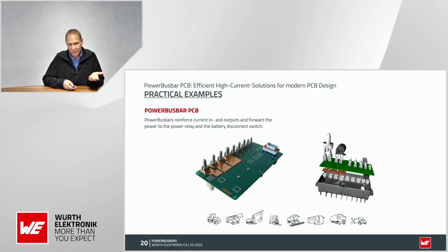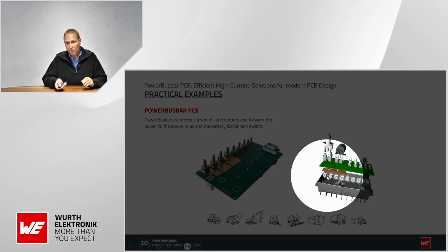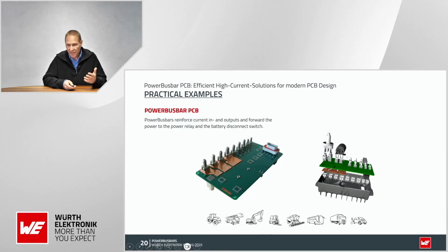So you have the bus bar on the top of the PCB and also on the bottom of the PCB. So you also have a compact design. And the bus bars are the only high current paths in these applications, so the rest of the PCB could be standard.